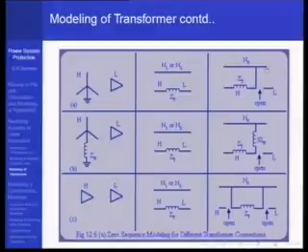This is the zero sequence diagram. For example, here what do you see? A circulating current can flow in this particular winding. If the zero sequence current is circulating in this winding, it won't be seen in the line, so you have kept it open here. But a circulating current here means there is corresponding zero sequence current in these windings also by transformer action, and therefore looking from this point, the total leakage impedance of the transformer gets a path to the ground, but is seen as open from here. If there is a ground impedance, then 3 times the ground impedance has to be added.